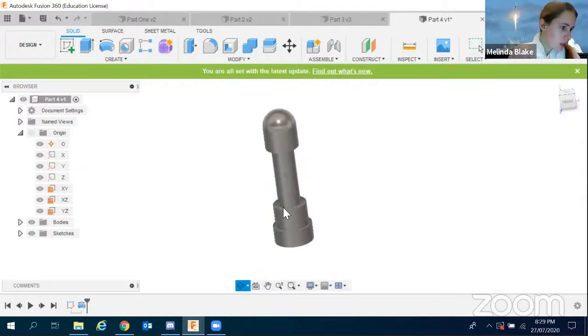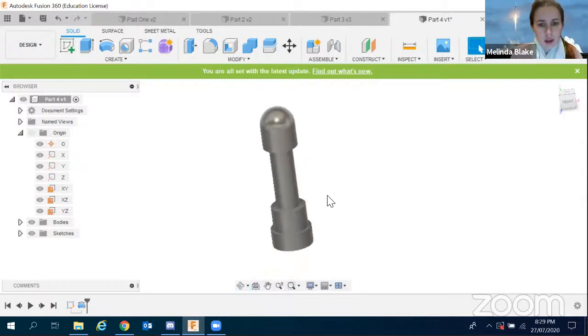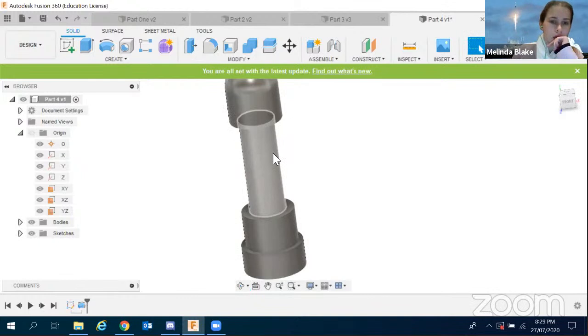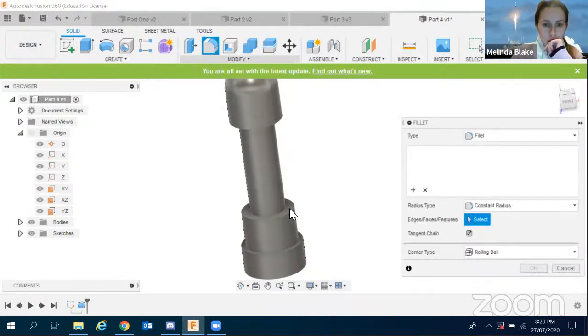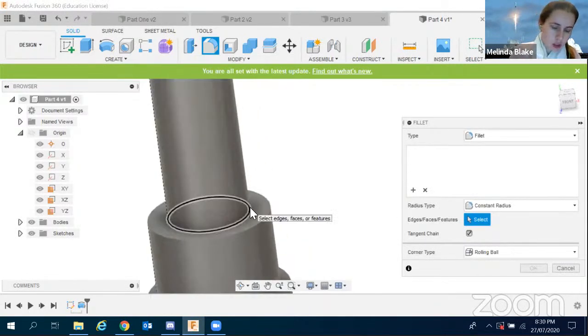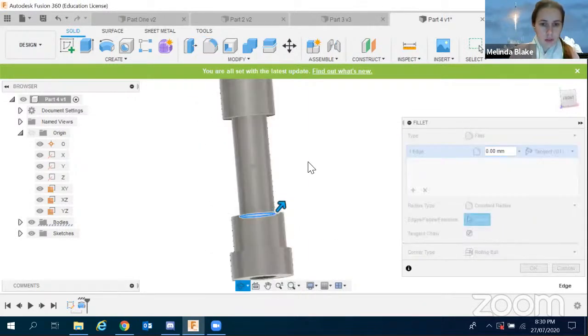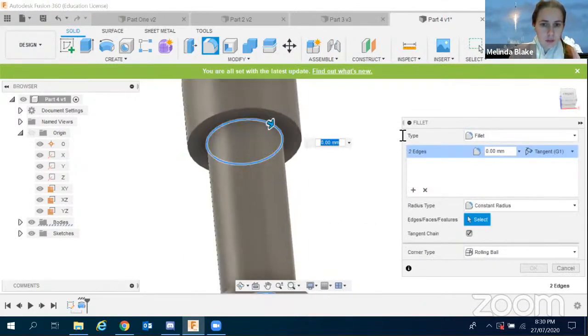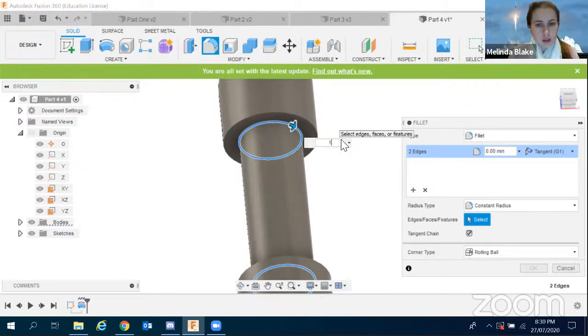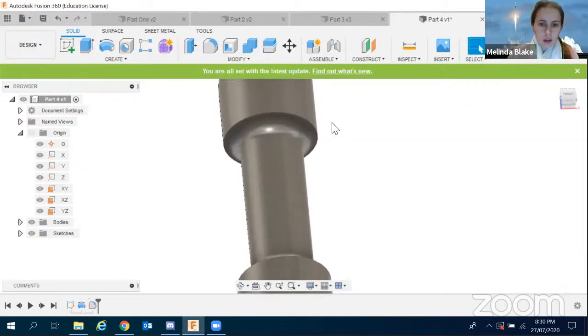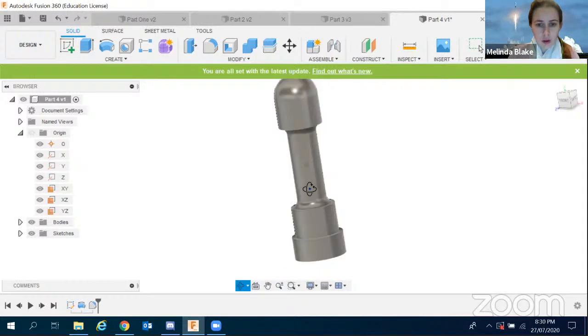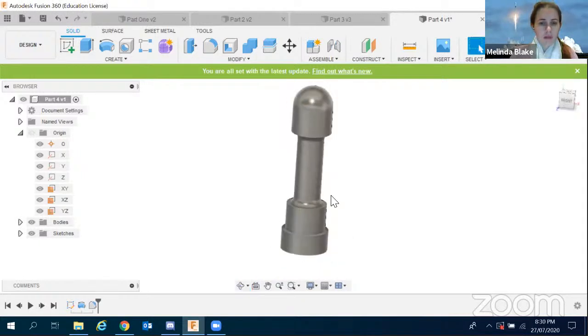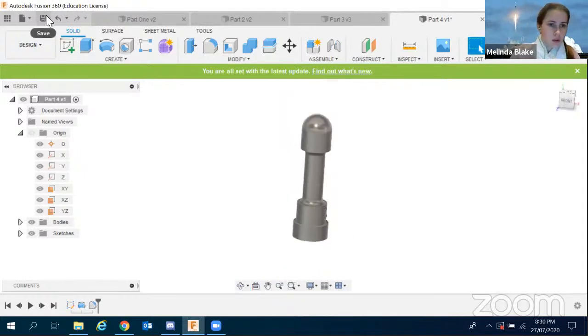Okay, the only thing that I need to do is add in those radii that I left out because they're a lot easier to do in a 3D geometry. So I'm going to grab that Fillet Tool again one more time. And the Fillet Tool also works on circles and on curved lines. So I can just select that circle there, and I can select that circle up there. And those both have a radius of 1. So we'll put in the number 1, hit enter, and we can see we've got the radii there. Okay, so that's using the Revolve tool to make something round in profile.